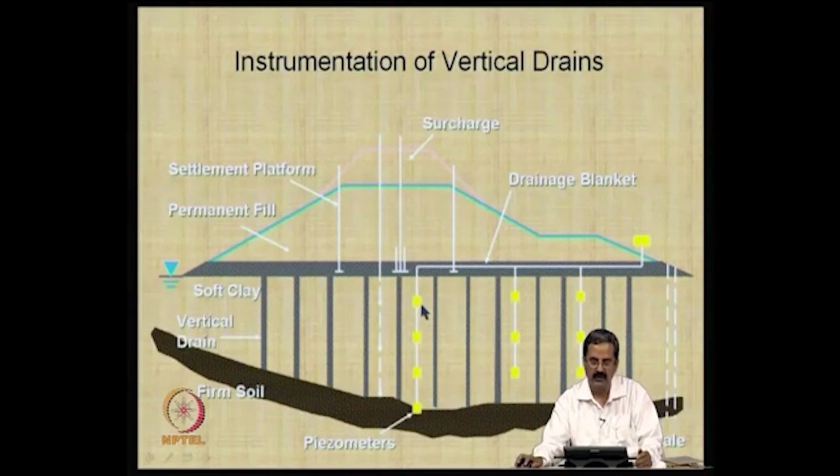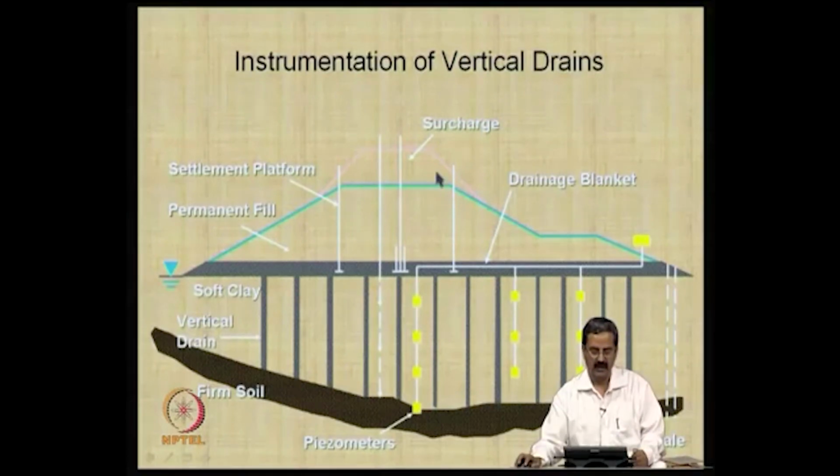So, what we do is that these pore pressures are continuously measured, at some frequency of intervals. Once you measure the pore pressures and settlement gauges, you will be much more comfortable. That is a very important concept here: instrumentation is a vital component, particularly in soft soils. So much work was done on these lines, where you apply some stress, then measure pore pressures and measure settlements.